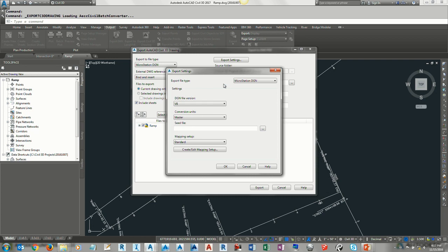So even that command runs some routines in the background, brings down all civil entities to AutoCAD. This command, if you have text, sometimes you will get issues with the conversion of drawing to DGN if you have used explode. But we found burst, if you are converting AutoCAD to DGN, burst works before you run this command.